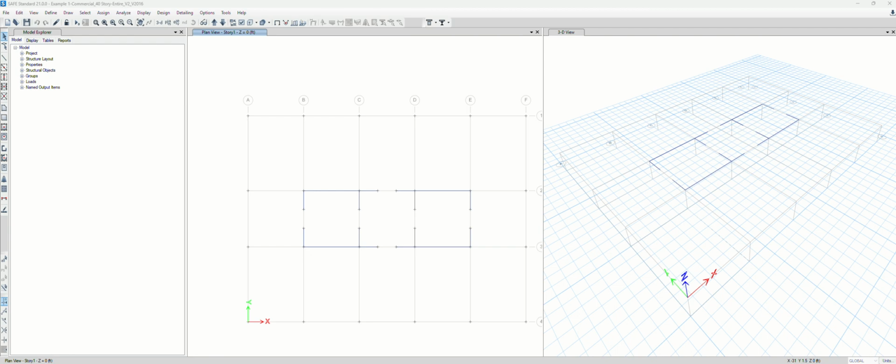And also I'm gonna create a section for slab section, which is gonna be mats. Default is slab 1. I'm gonna change this to mats. Maybe I'm gonna choose 84 or 96. 84, let's say 84 inches. We have a type of a mat here, right? So I'm gonna change the concrete strength. So 5,000, 84 inch thick mat. Just define the properties, section properties.